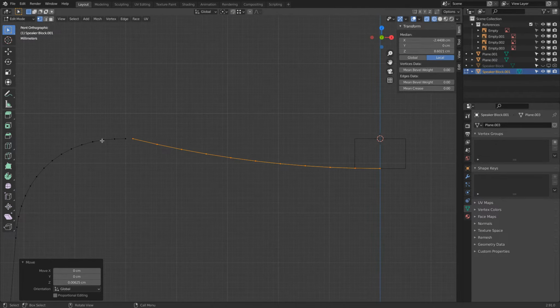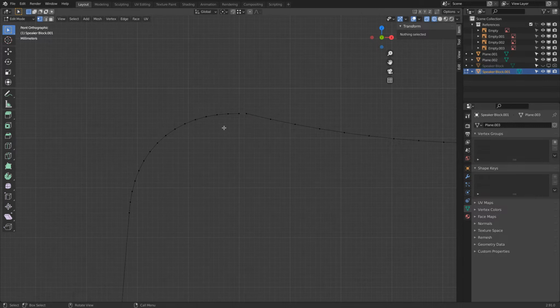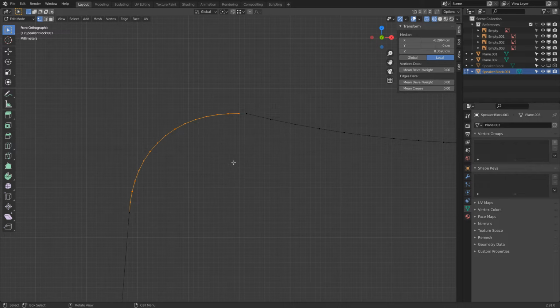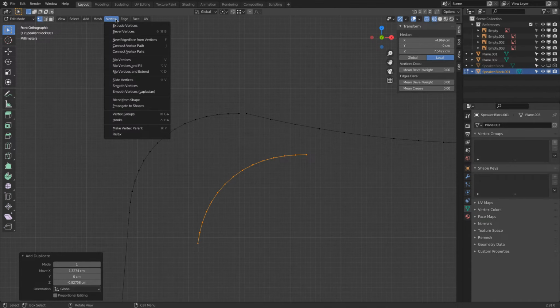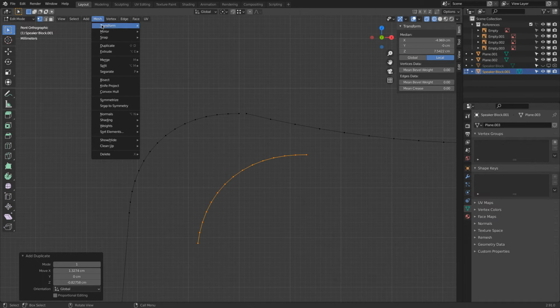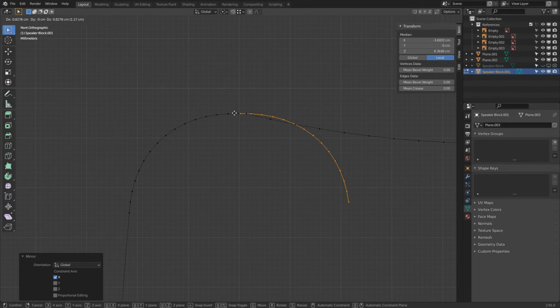And now we need to figure out, okay, so from here, how do we blend this one over? Let me show you something. A A, C, and then we paint over all this. Escape. Shift D and move this to here. Again, this is the x-axis, so we will, where's the mirror command? Mirror along X. G, bring this to there.